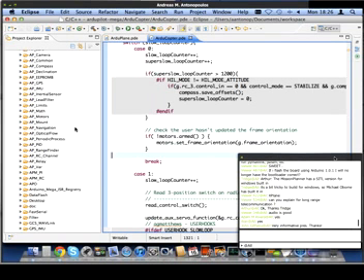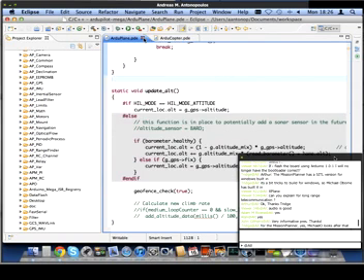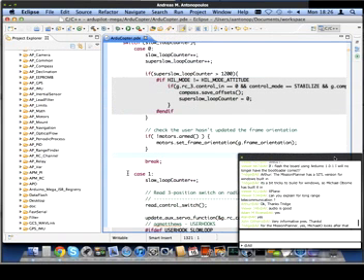Worth waiting. Okay, so what I wanted to go through was a top to bottom code walkthrough of how flicking the switch on your controller gets all the way down to the motors. So when you've got your controller, you've probably seen the Mission Planner setup screen where you can set what each of the 6 positions of your switch, or however many positions your switch has, correspond to in actual flight modes like loiter or whatever.